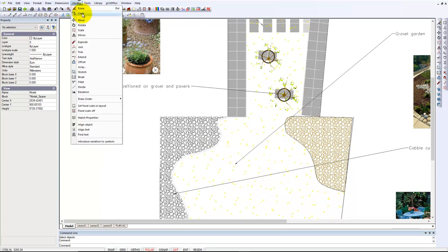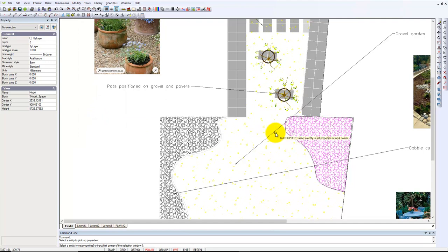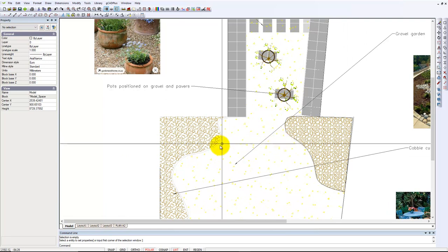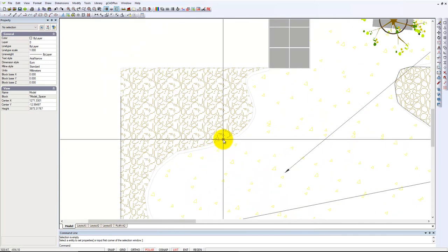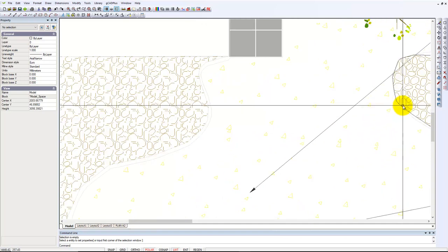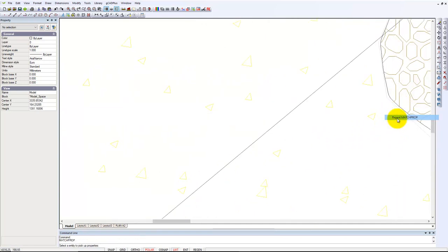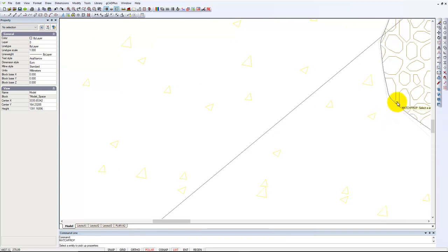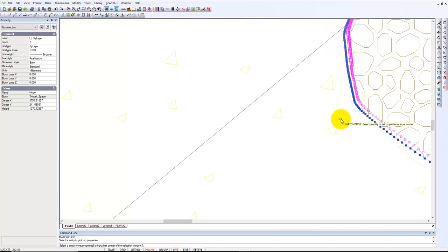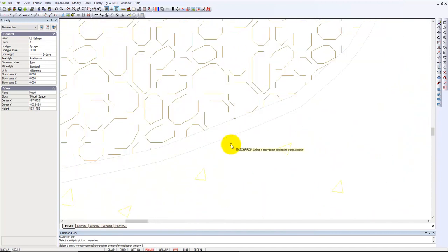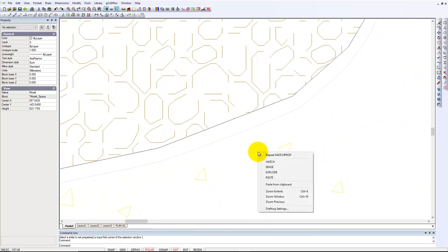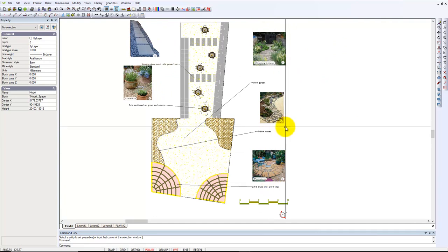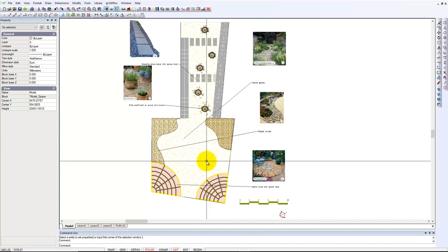We can modify and match properties from that one to that one. There's some adjustment to do with colour. It's probably the colour of the... We zoom in here and match properties, pick up that polyline, not that one. Zoom in a little more, we want this one, and we'd like it applied to the inside of that one. And now let's zoom extents and see how we're going. So hopefully that helps our users improve their hatching.